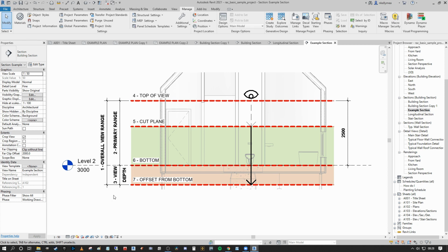But after the 1220 mil or the 4 feet value, they convert themselves into the beyond line style as well. I appreciate that can be a little bit confusing, but when you understand the function of the objects, you realize why they don't follow the same rule as all the other elements within the view depth.